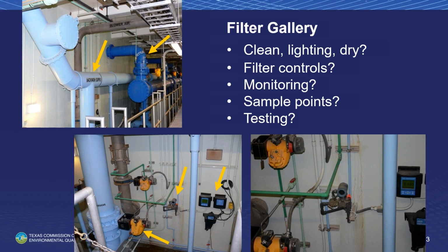But we can come in with our equipment and actually take the actual readings off the turbidimeter and compare what's actually been done against what's going to the SCADA system. And I'm sorry to say that quite often we find falsification of records because of that, you see. So there are various problems with testing when you're dealing with filters.